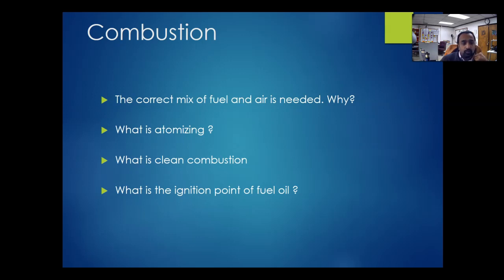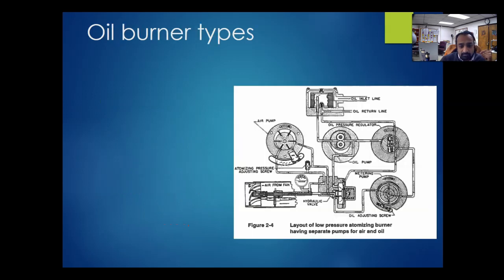This is when the fuel will start to ignite and continuously ignite. I've seen 500, 550, and also I've seen 600. Depends on the fuel and its grade, but for fuel oil number 2 to meet specification, it has to be around 500 degrees Fahrenheit.